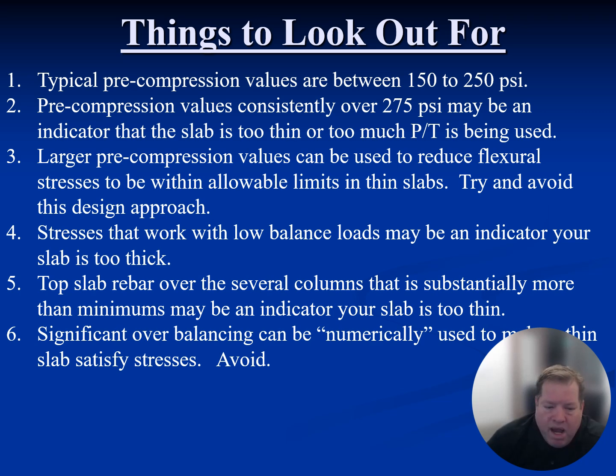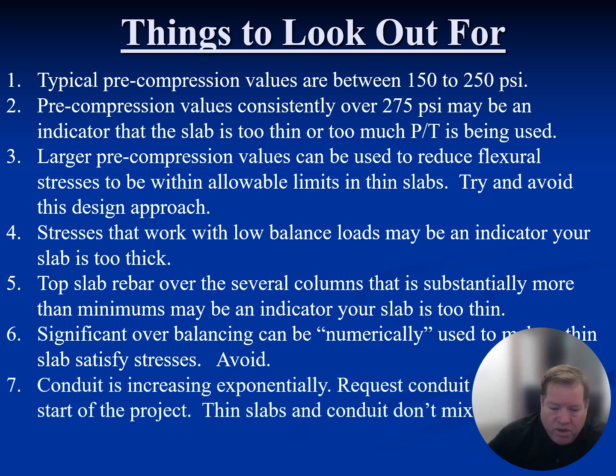The problem with overbalancing is that when you stress concrete 3 days after you pour it, there's no ceilings, there's no partitions, there's no live load. It's just gray concrete. And so if you're cranking up with 300% balance loads and the vast majority of that load it's going to resist won't be there for 6 months, that's what leads to blowouts, to cracking, to over-cambering. So again, it's a numerical solution to make a thin slab work, but it's going to cause you a tremendous amount of potential problems during construction. So please try to avoid that.